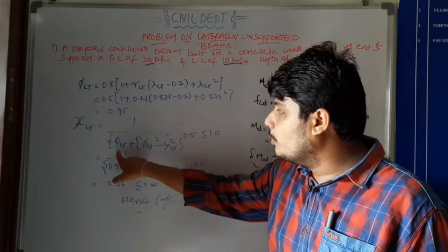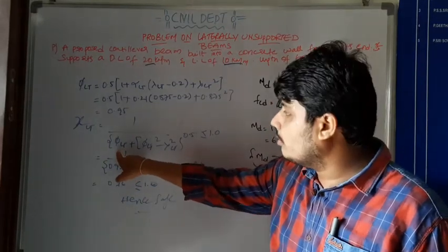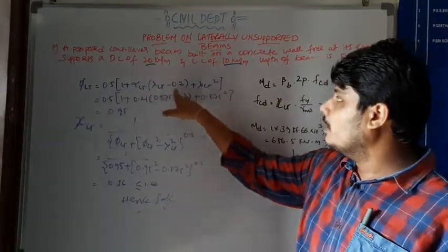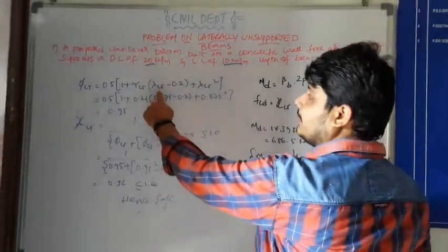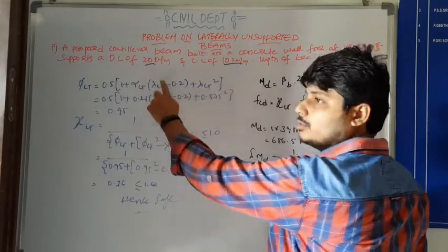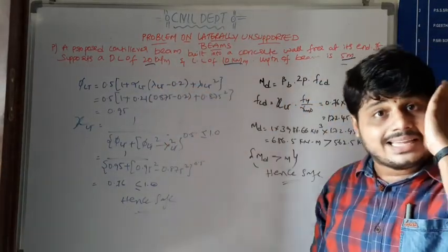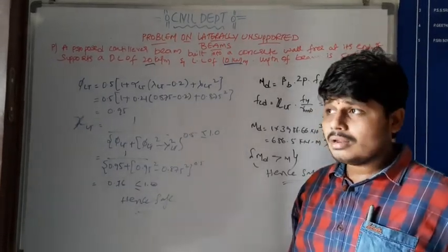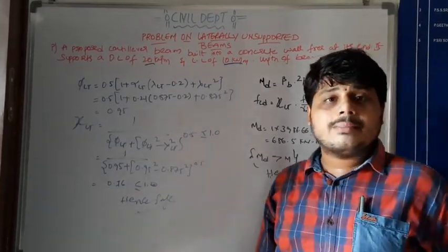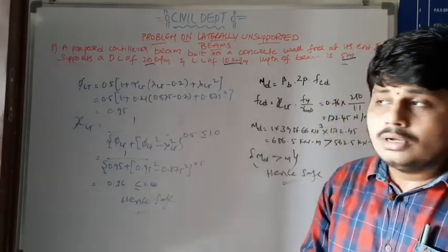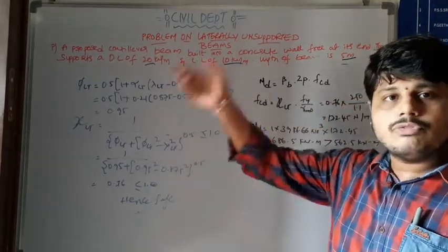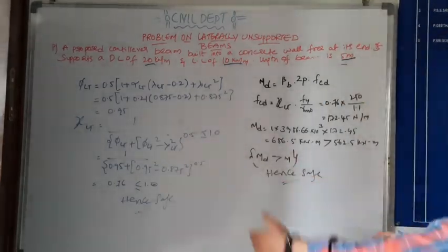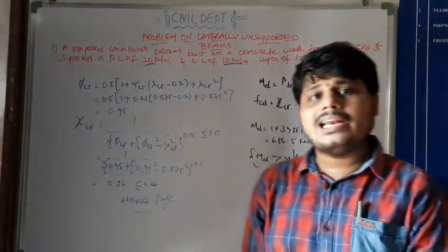While solving this formula, we don't know the value of pi LT. So to calculate pi LT, we should solve the formula with alpha LT and lambda LT. We don't know lambda LT, so we should calculate the earlier formula for lambda LT. Lambda LT is nothing but root of beta B into ZP into Fy by MCR, so we should calculate MCR. So these are the steps to solve the laterally unsupported beam.